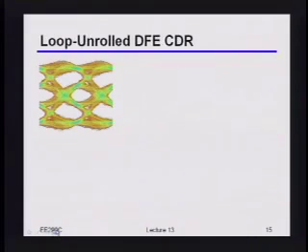Okay, so, in case you thought we were done, there's still a little bit more fun to be had in CDR. I guess nobody this time around did it, maybe because I banged your heads on how annoying it was to adapt these things. But nonetheless, loop unrolled DFEs are still fairly common and popular in the real world. If you do a loop unrolled DFE, your life is fun not just because of adapting the coefficients for the DFE cancellation itself, but it has some pretty direct implications on the clock and data recovery as well.